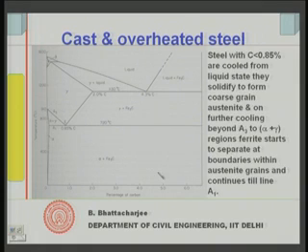You see, steel with carbon less than 0.85% when cooled from liquid state solidifies to form a coarse grained structure, austenite. This is austenite, if you recall our last class discussion. So, first you will have austenite and liquid, and then below 0.85 you will have austenite formation, and up to the A3 line it will be all austenite.